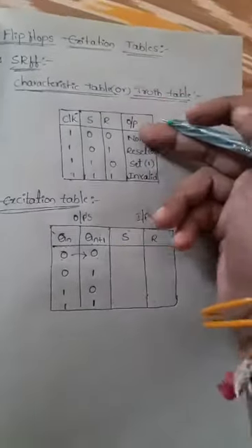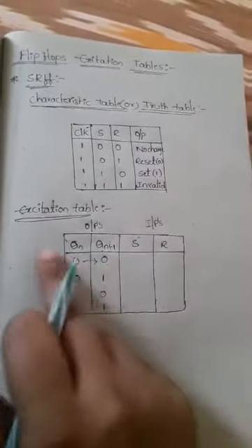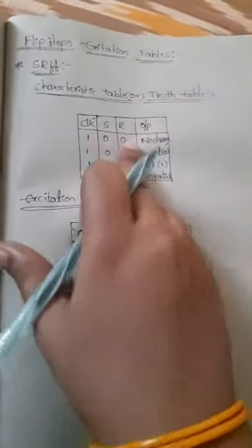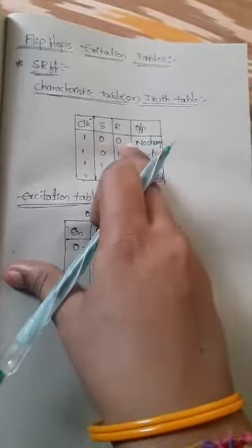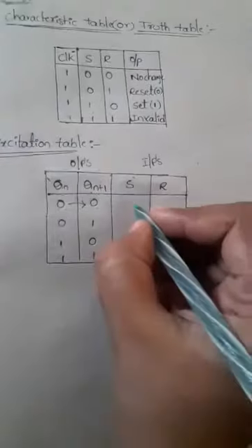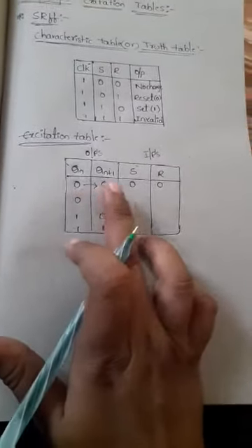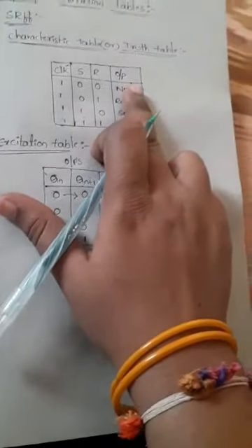After getting the comparison result, that result is compared again with the truth table. We got no change, right, the first result. The no change operation in the SR case is the input case 0 0, so you can write 0 0 as it is here. So after comparing, whatever result you collect is compared again with the truth table. In whichever case you get the no change operation, you write those values as they are.